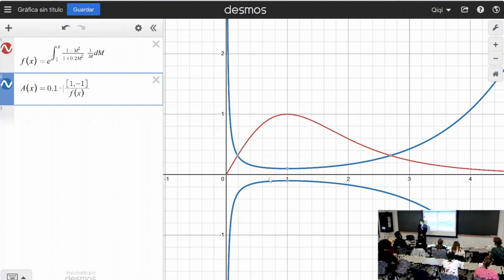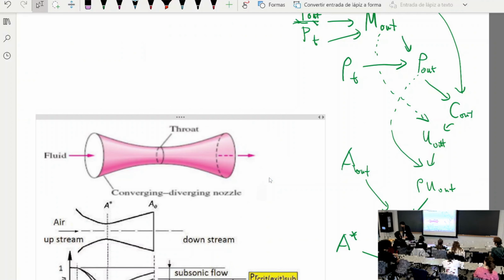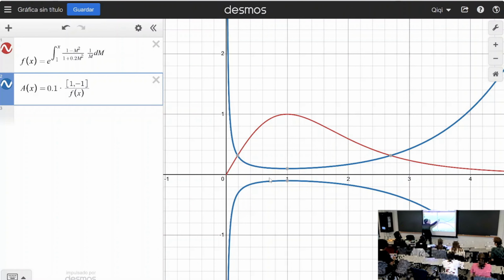Okay, so whenever you compute a rho u, mass flow per area, that is lower than the maximum, because the throat actually gets the maximum mass flow per area since it's the minimum area, right? So if this one has a lower than maximum mass flow per area, then the entire nozzle is going to be operating over here. There is no way the nozzle can operate over here. Do you agree? So the whole thing is subsonic.